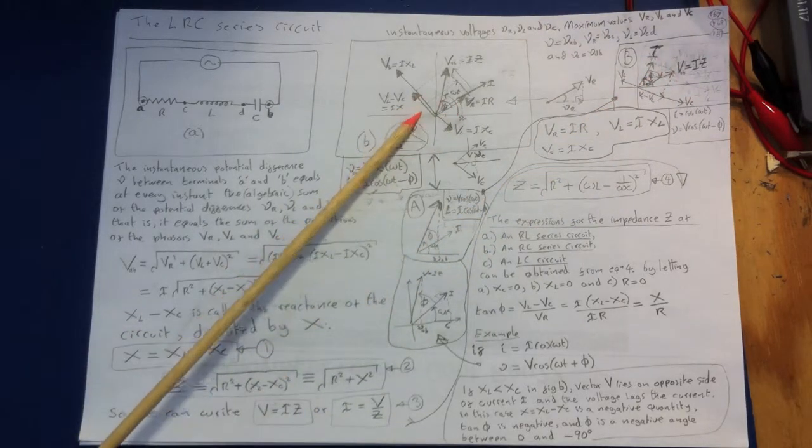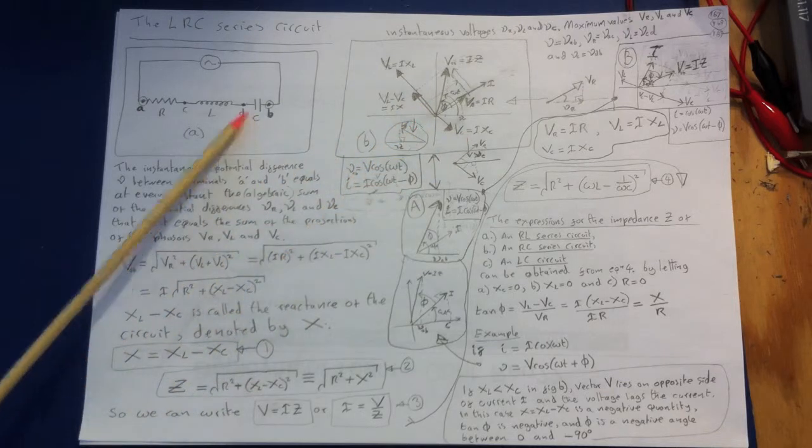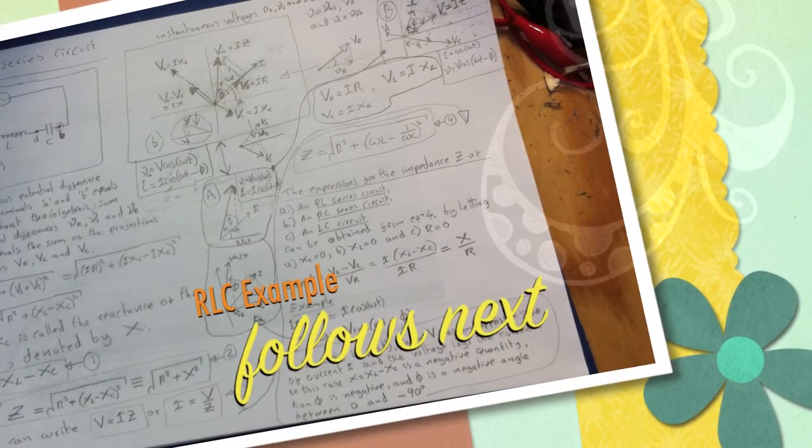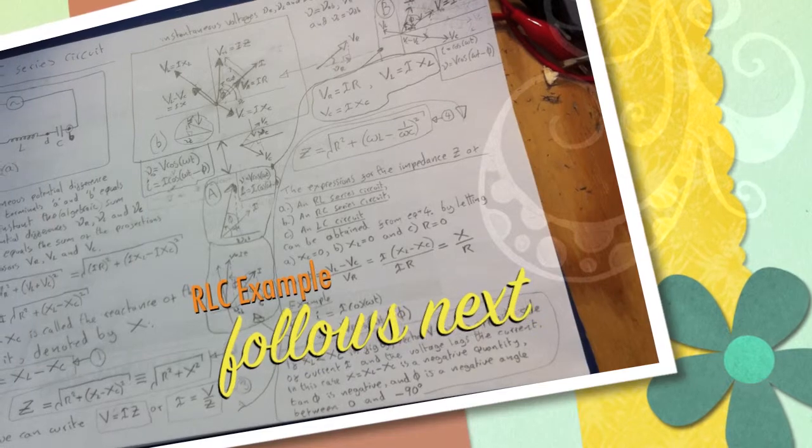The phase angle is a nice way of representing all the behaviour of these three components in a circuit. It's very useful. This analysis describes the steady state condition of a circuit, the condition that prevails after the circuit has been connected to the source for a long time. When the source is first connected, there may be additional voltages and currents called transients, whose nature depends on the time in the cycle when the circuit is initially completed. A detailed analysis of transients is beyond this intro set of lectures, but they always die out after a sufficiently long time, which in this case is a few milliseconds or so. Therefore, they do not affect the steady state behaviour of the circuits.